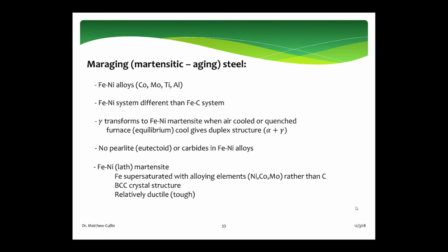And so here is the superstar of the steels, and that's Mar-Aging steel. Mar-Aging steel is a combination of martensitic and aging steels. So we know that the term aging is kind of reserved for precipitation hardening. So when we talk about aging, we're going to be talking about forming precipitates, and then it's also going to be martensitic, but it's a different type of martensite.